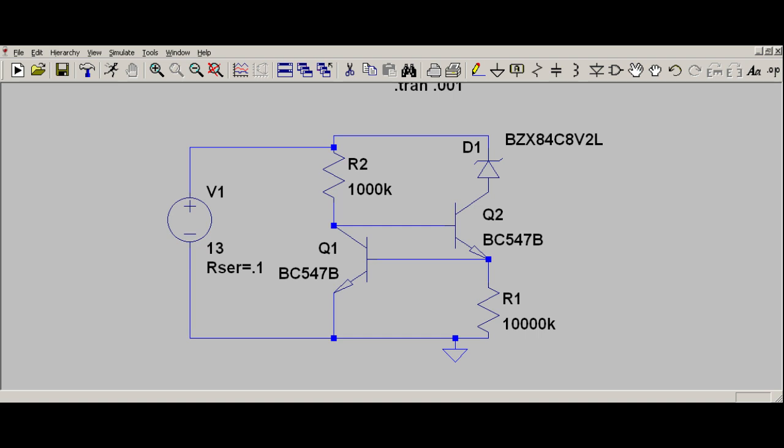At these very low current levels, a current sink like this will deviate quite a bit from the ideal behavior, because the base currents of the 2 transistors will be very similar to the collector current of Q2. So in theory this circuit should sink 60 nanoamperes, but the simulated circuit showed a 95 nanoampere value.